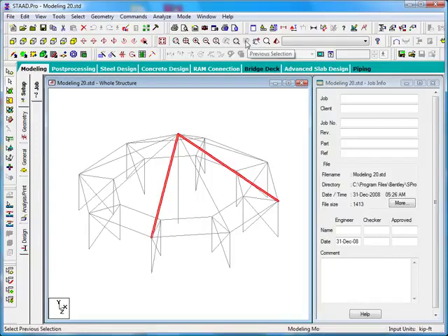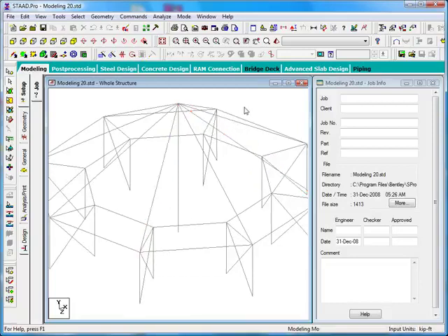I believe that the reason that it's included on this toolbar having to do with zooms is that it's a common problem that you might have something selected and then decide that you want to window in on it and accidentally click and lose your selection set. And so when you're in the mode of working with your zooms, you might want to just come back and quickly recover that selection set. So that's called the previous selection icon.